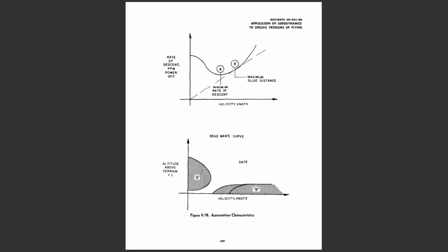In addition to aerodynamic forces which act on the rotor during autorotation, inertia forces are also important. These effects are usually associated with the pilot's response time because the rate a pilot reacts to a power failure is quite critical. The time necessary to reduce collective pitch and enter autorotation becomes critical if the rotor inertia characteristics are such as to allow the rotor to slow down to a dangerous level before the pilot can react.